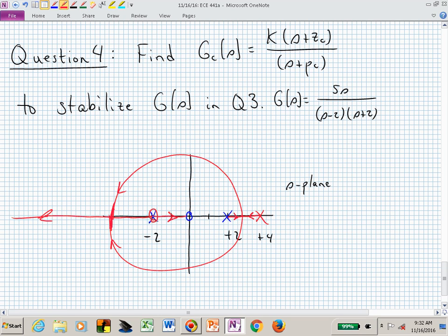And now what do we have? Do we have an upper bound on the stability value for K, a lower bound? Do we have any Ks that we can stabilize the system with? We now have a lower bound, don't we? We have to crank up the gain enough to move us into the left half plane. We have to crank up the gain to get us beyond those 2 imaginary axis crossings.